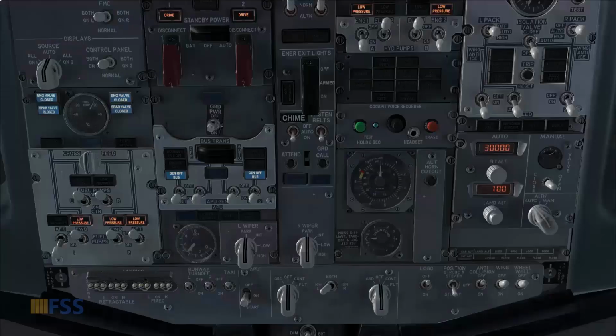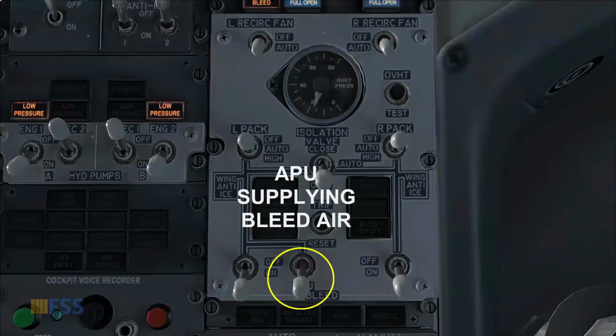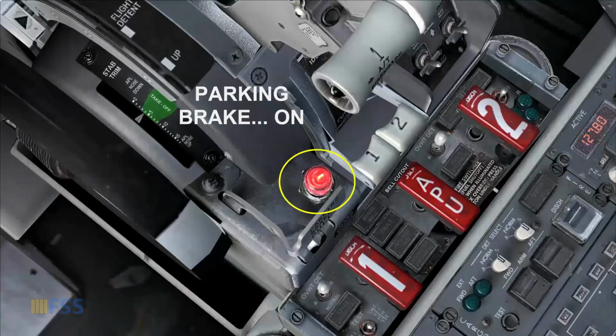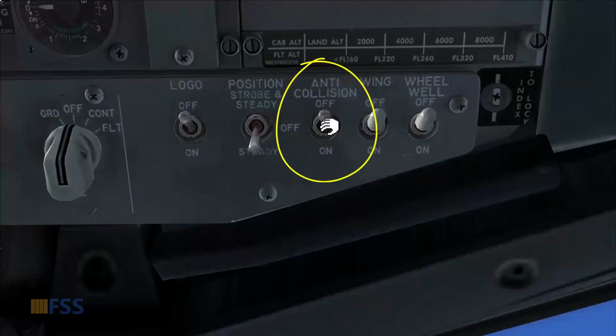The pre-flight check is completed, the APU is running and supplying both the electrical power and bleed air to the aircraft system. Now before we start the engine, make sure that the parking brake is set and the thrust levers are set to idle. Turn on the anti-collision light to notify the ground personnel of an imminent engine start.